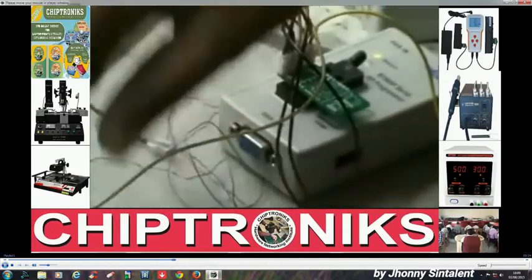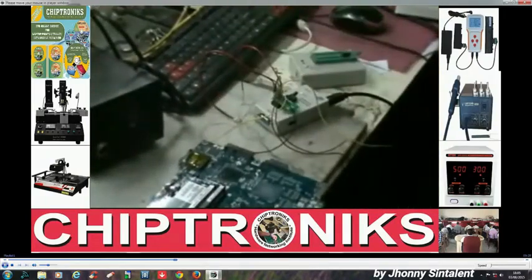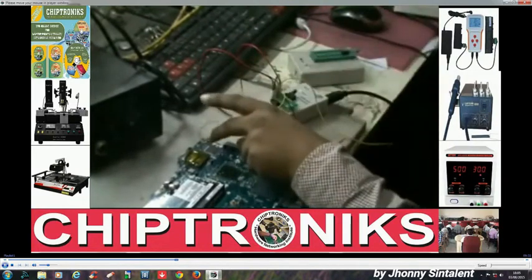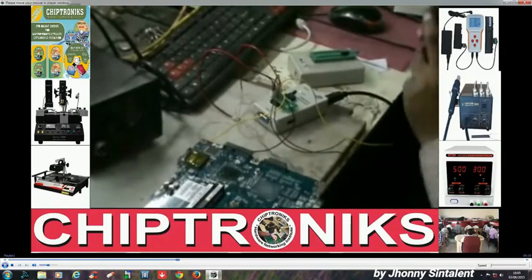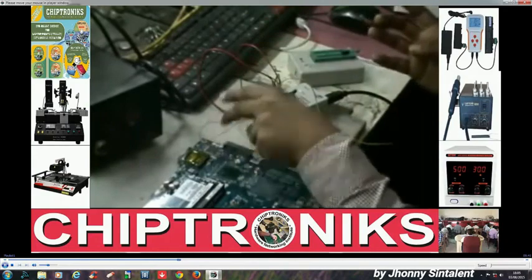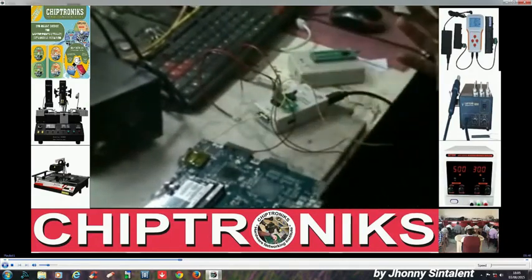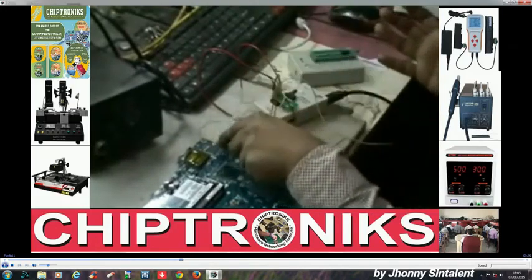So what we will do is we'll supply the three things as discussed in the very first class. I have said that any integrated chip requires three things: supply, reset, and clock. And in my IO class, I've already said this IO controller requires a supply of 3.3 volts, reset is EC reset, and clock.